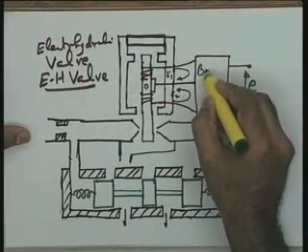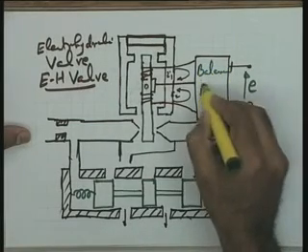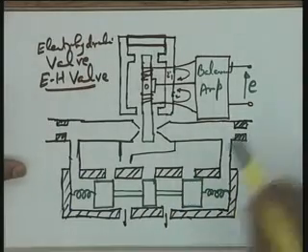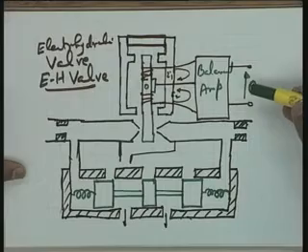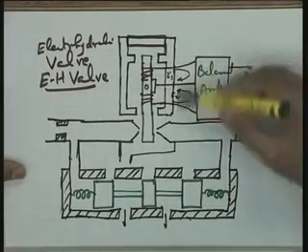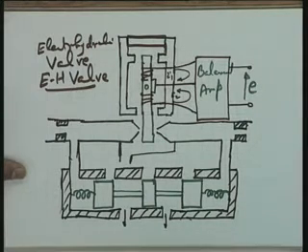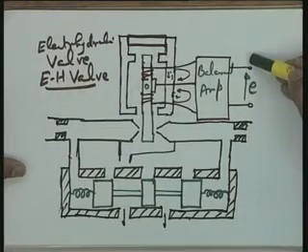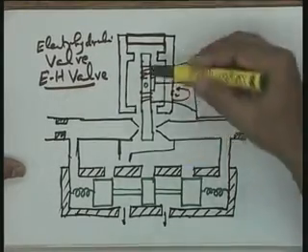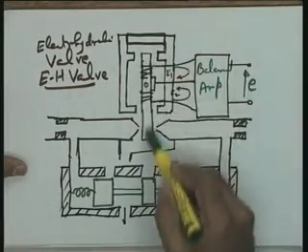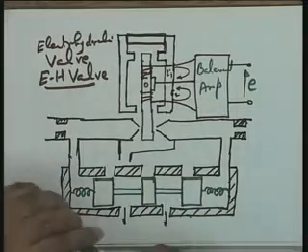This voltage signal I give to a balanced amplifier. Now what is this amplifier going to do? When E is equal to 0, what will happen? The currents I1 and I2 are equal. The amplifier is designed that way. Amplifier design I am not going to carry out here. I am going to give you the characteristics of the amplifier, and I leave the amplifier design to you. When E is equal to 0, the two currents are equal, the two fluxes are equal and opposite, and hence the net movement of this particular armature is going to be 0.